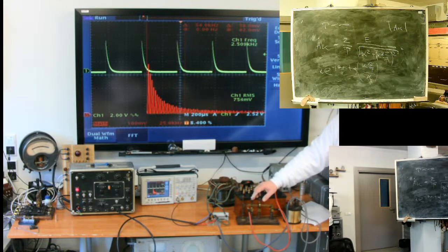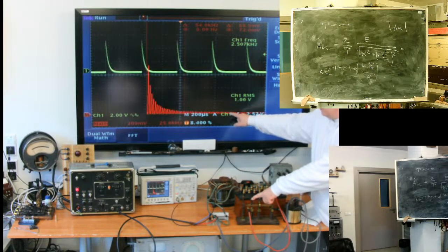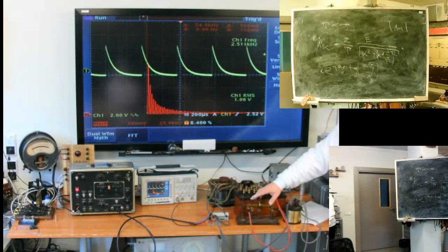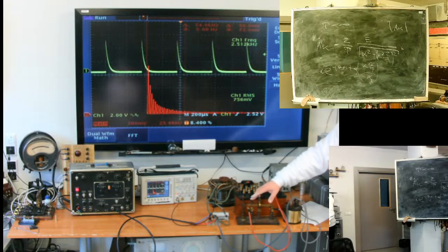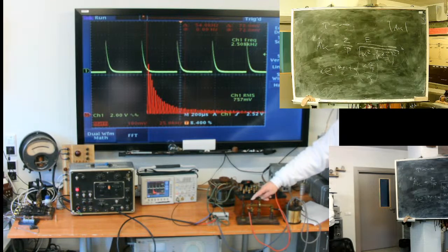But for example, you use a smaller capacitor in a snubber network. This means the recovering voltage on, for example, an IGBT or MOSFET transistor grows faster. The frequency range of disturbance is broader, and you get disturbance in what appeared to be a safe area where communication occurs. Or you disturb some public network and have a problem with FCC.